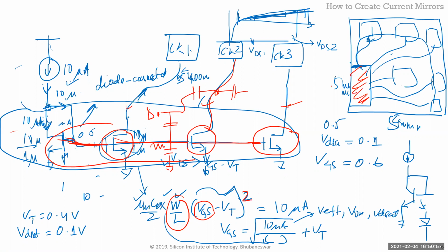And same thing, if you're doing long routes and you have IR drops here, no big deal. If you're taking a gate voltage, you have an R and some current flows through it and creates an IR drop, a huge difference in your bias current. So that's the other reason why we ship currents instead of shipping the gate voltage to all the places.